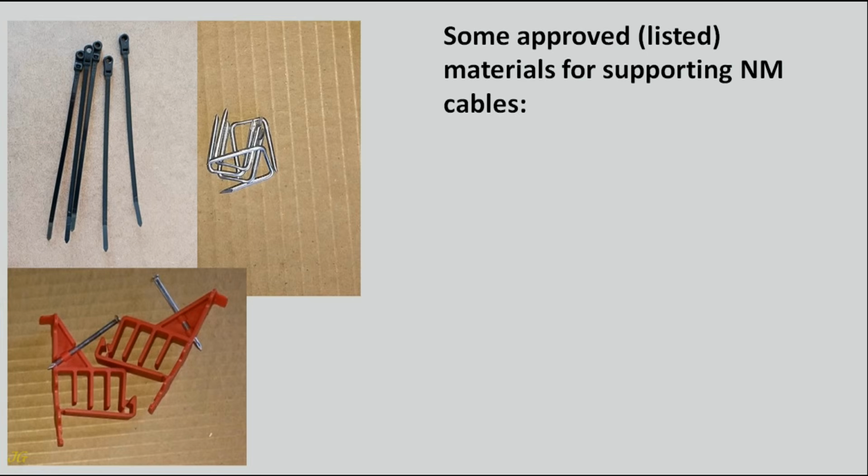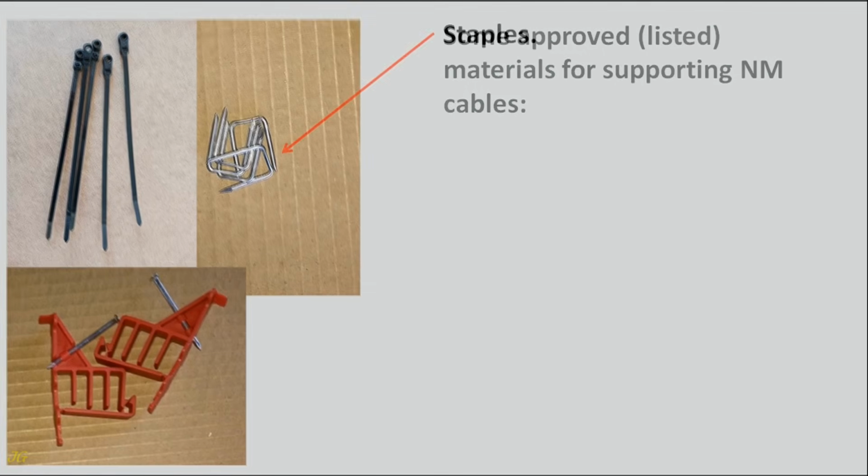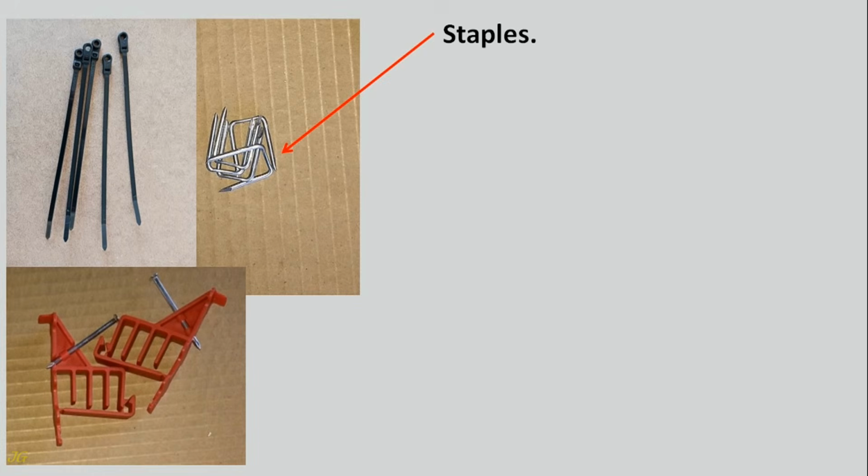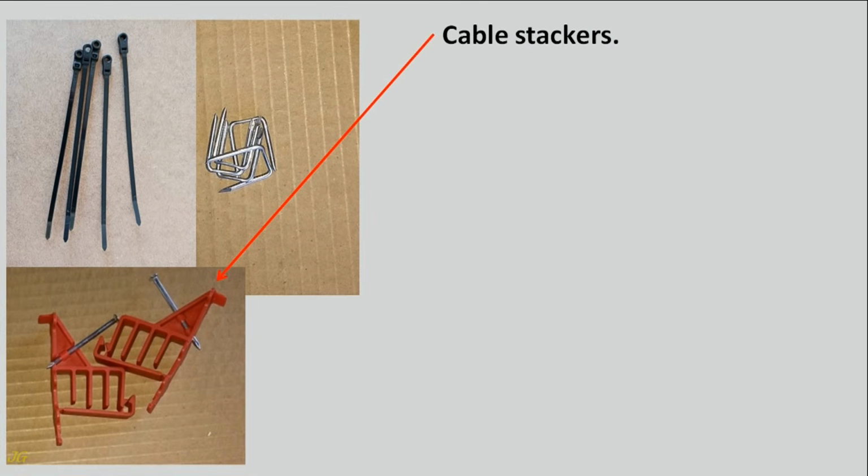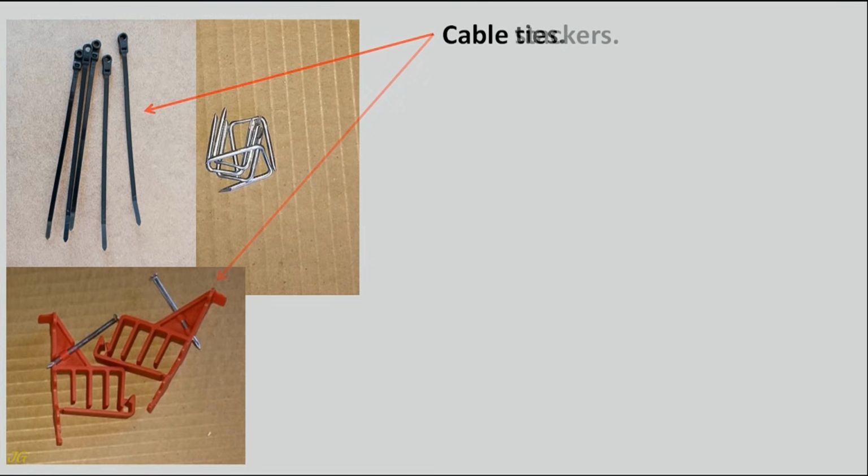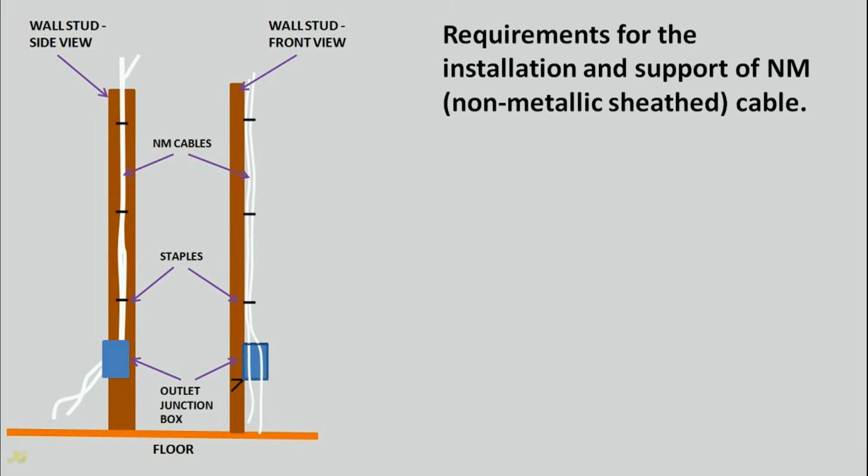Some approved, listed materials for supporting NM cables: staples, cable stackers, cable ties. Requirements for the installation and support of NM, non-metallic sheathed cable.